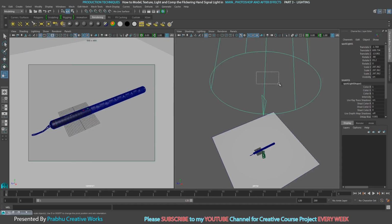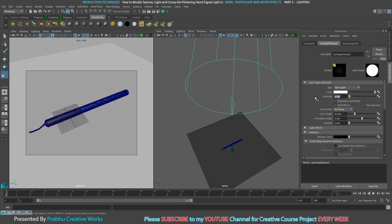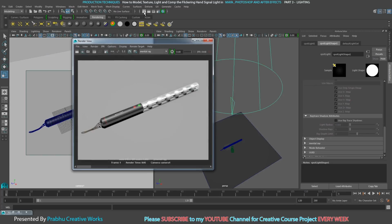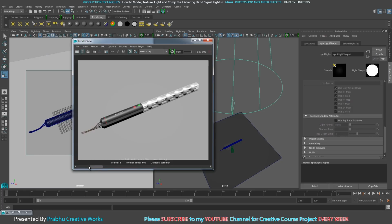So I will select this object, select the light, go to the attributes editor and reduce my intensity to 0.1. So it's very low, and then go downside. In the shadows tab you want to disable use ray trace shadow. So I will open my render view and click this button. I will click this button to keep the image for our comparison. Click the render button.